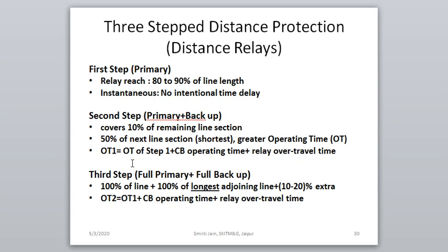The third step will include the 100% primary protection of the considered line plus 100% of backup protection of the longest adjoining line, or plus 10 to 20% extra, that is some one more adjoining line. So the operating time will be greater for the third step.